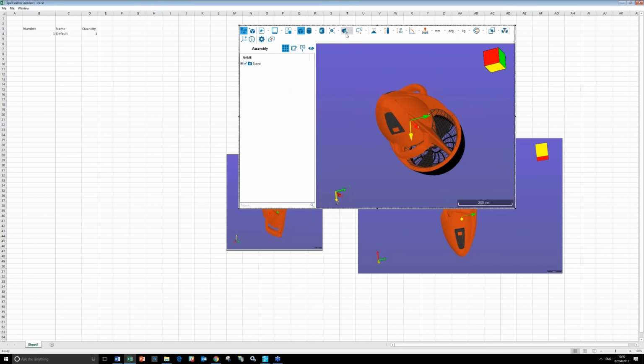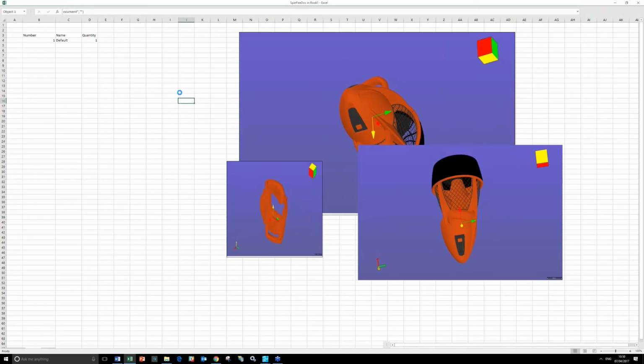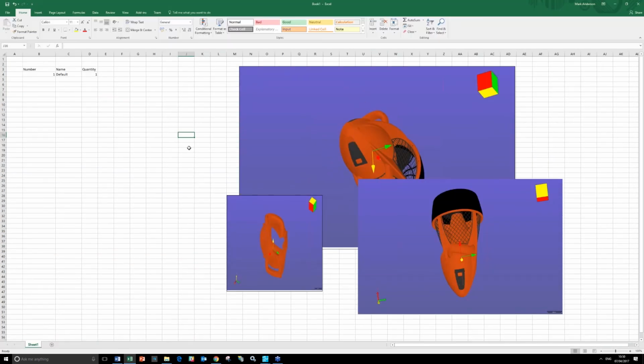So I can do my session cuts, do the measurements, and look at any user views. I can do some markups, and these can then be saved in the workspace. When I click off it, it'll ask if I want to save it, and I can say yes.